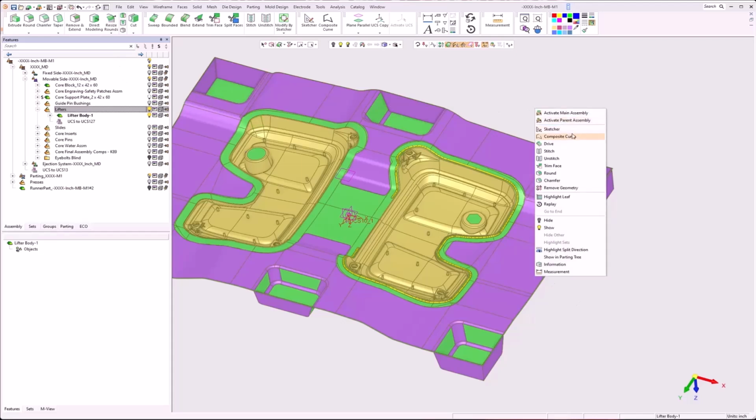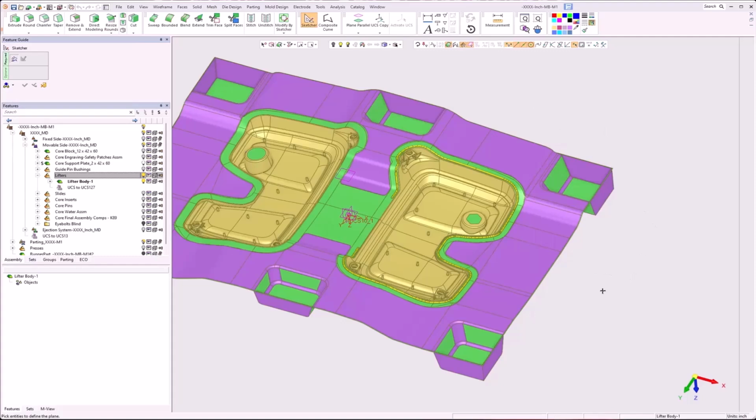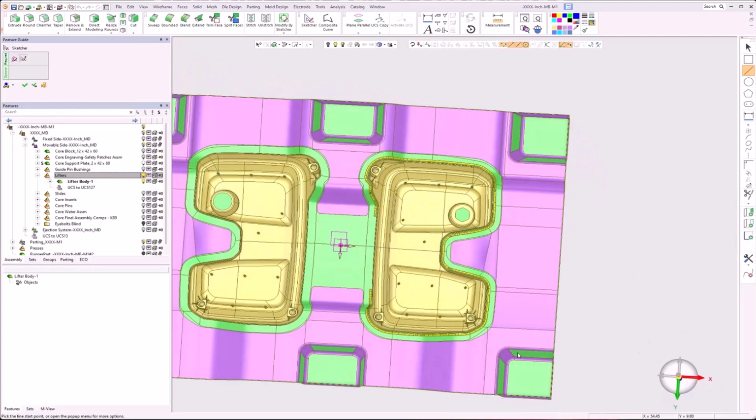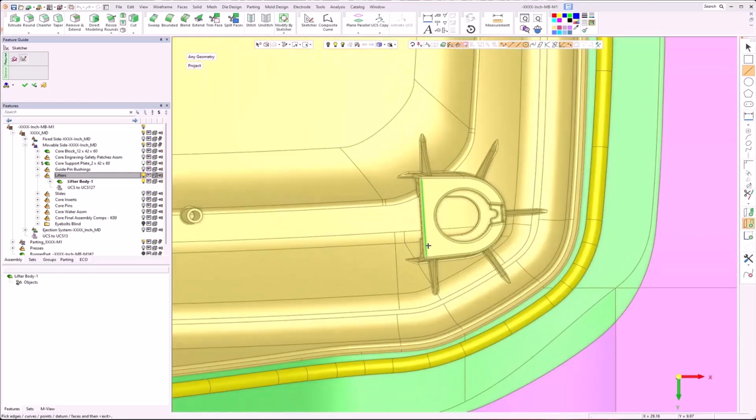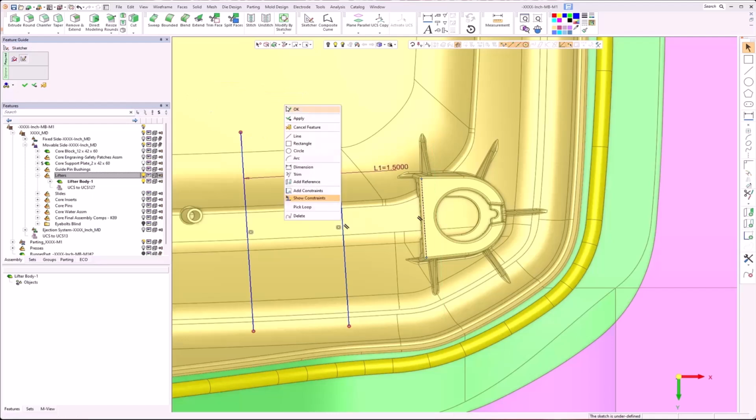We are going to use Sketcher. We're going to take the default plane. Depending on your part, you may need to make some planes in local areas. In this case, I can get away with just using the default. I'm going to add reference geometry. I'm going to pick this edge. My lifters travel normal to that, so that's why I'm picking the reference. I'm going to make a line. I'm now going to offset that line, flip, add a couple more lines to finish up the rectangle.